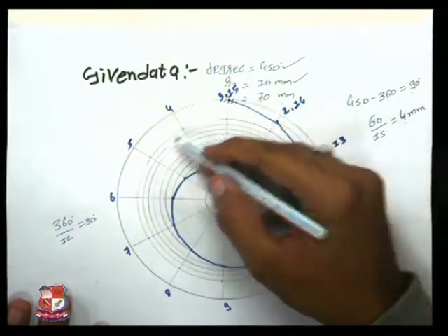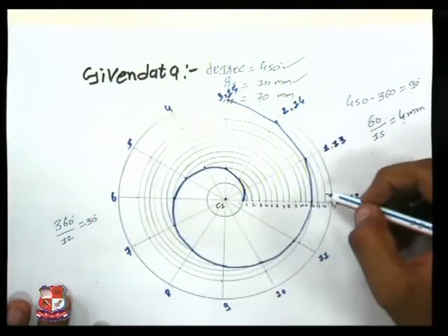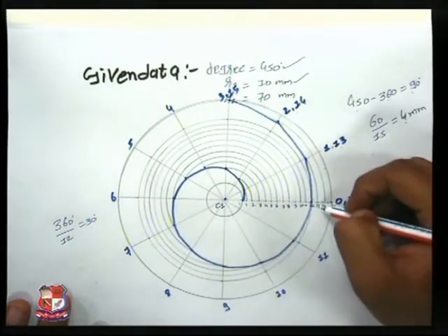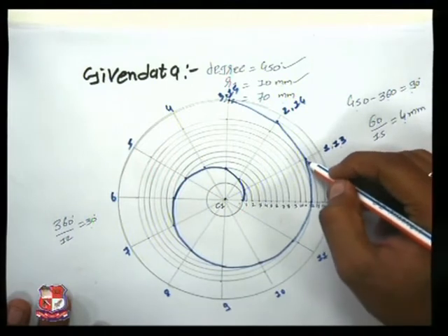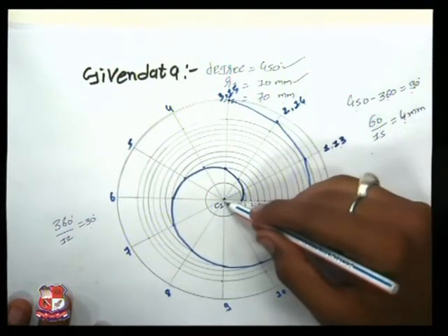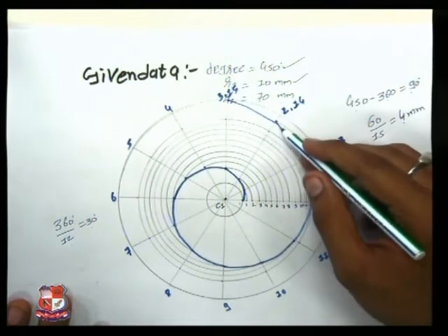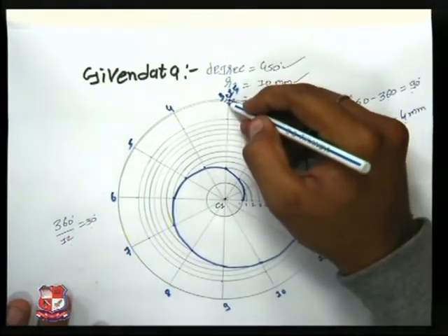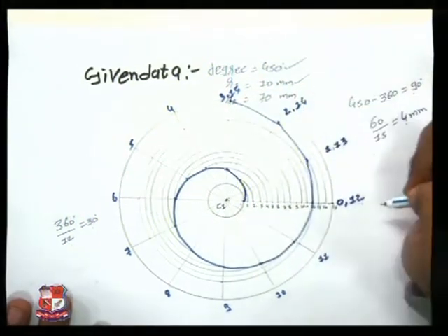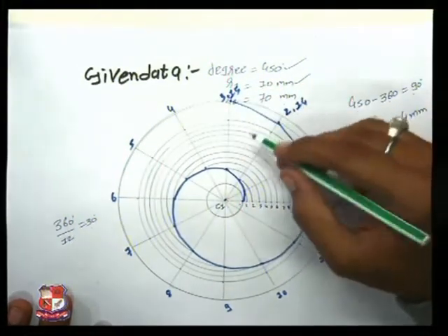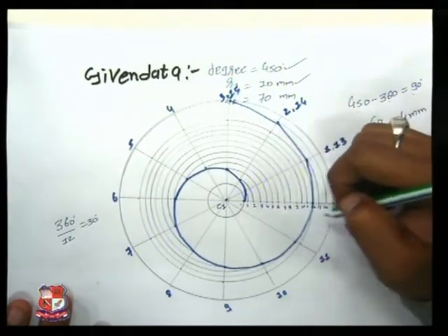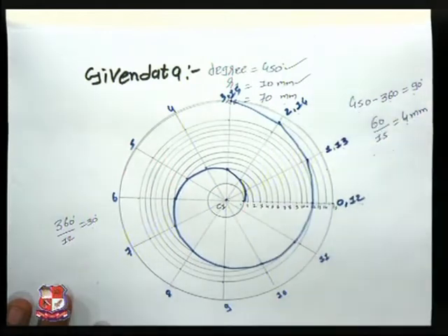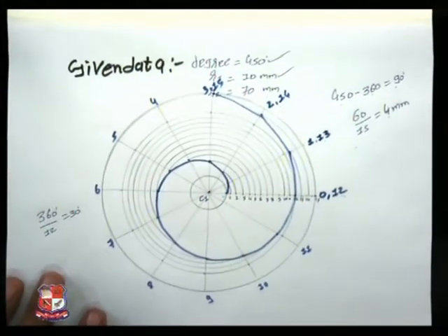C1 to 6, line till 6, C1 to 12, a full circle, C1 to 13, which means only 30 degrees additional, C1 to 14, only 60 degrees additional, and C1 to 15 would be directly the outermost point over here. Now from the continuous arcs we have got several points. We have joined these points and we have got our Archimedean spiral.